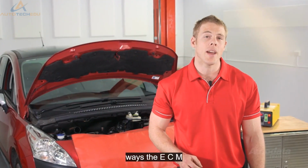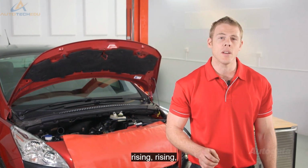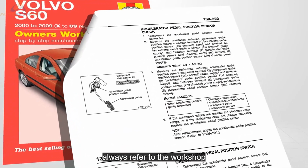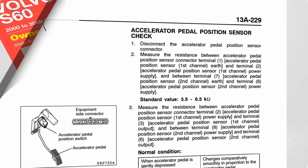There are three different ways the ECM may interpret accelerator pedal data: equal rising, rising falling, and split rising. So before any diagnosis is made, always refer to the workshop manual for the correct operating procedures for that vehicle.